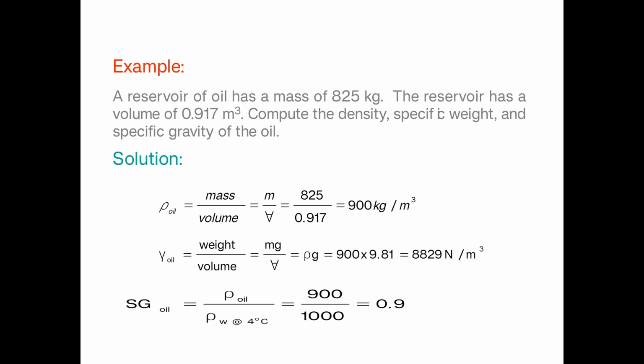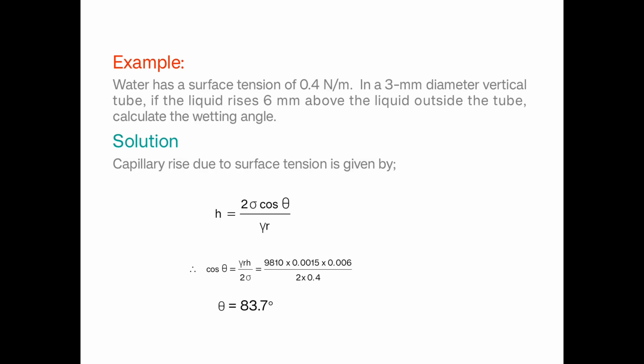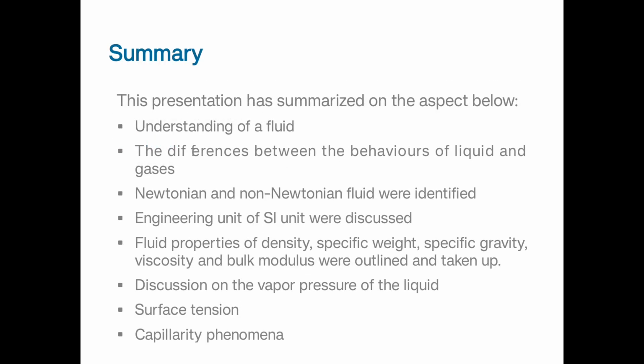And here are a few examples to account again for the same concepts being expressed here, along with the measurement of the capillarity and the capillary rise for a water surface in a 3 millimeter tube, as highlighted here very clearly. So that's it about our complete explanation of understanding the fundamentals of fluids and their properties.